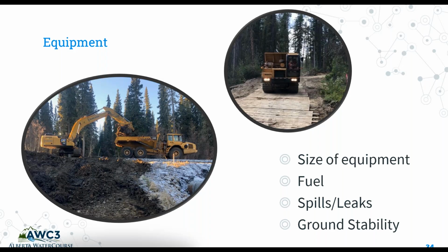Equipment. So the equipment you need on site can vary on the scope. You'll want to consider the size of equipment you need. Where is this equipment parking for fueling? Is this equipment free of any spills or leaks? And ground stability can play a factor as well. If you are working over steep banks, large equipment can cause stability issues.